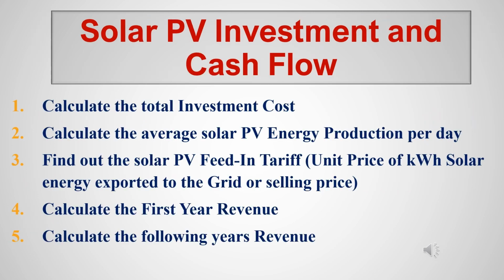Solar PV investment and cash flow. Calculate the total investment cost. Calculate the average solar PV energy production per day. Find out the solar PV feed-in tariff, the unit price of kilowatt-hour solar energy exported to the grid, or selling price. Calculate the first year revenue. Calculate the following year's revenue.